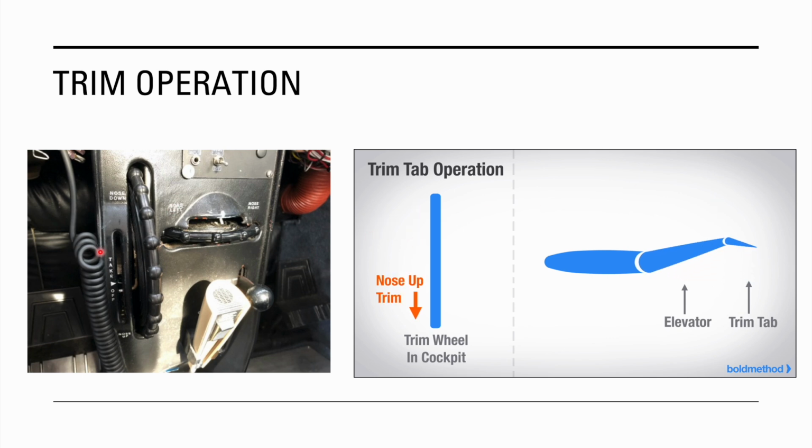So there's no set or established settings for trim. It's really just based off of feel. So it really depends on how much airflow is going over the control surfaces. So anytime you change your power setting, you're going to have to change your trim.